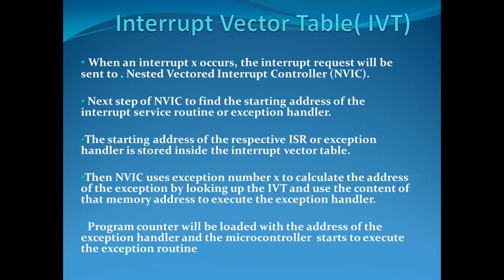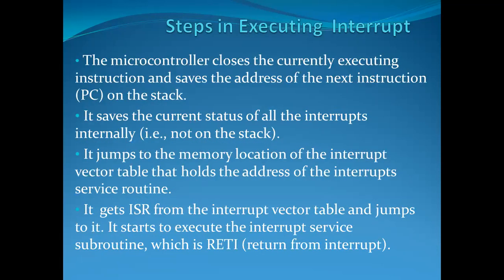The program counter is loaded with the address of the exception handler and the microcontroller starts to execute the exception routine.